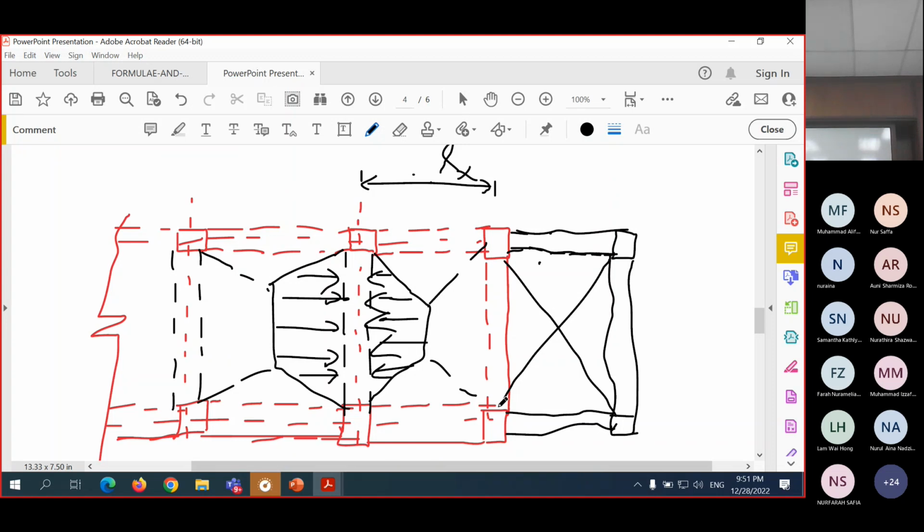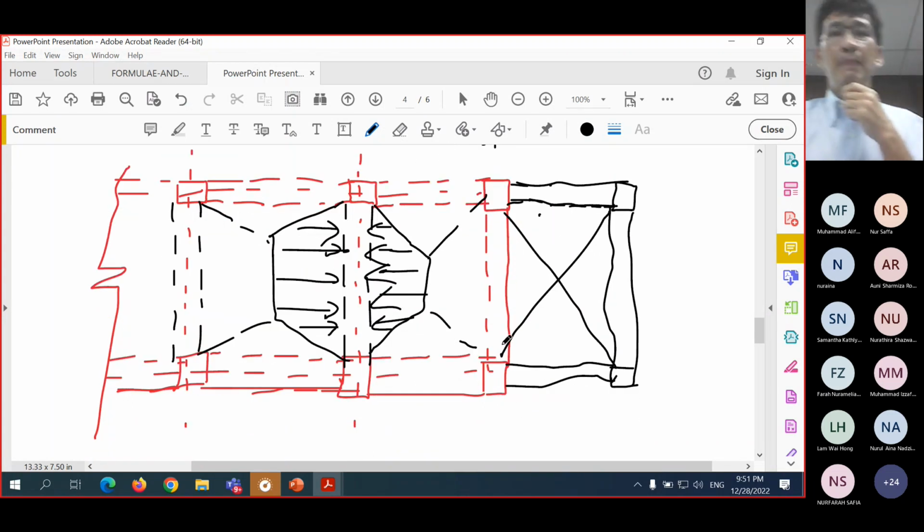depending on the standard that you refer to, sometimes for a certain thickness they give you kilonewton per meter square, which means if you look at the wall, 1 meter square with that thickness is a certain kilonewton. Then to get kilonewton per meter, you need to multiply with the clear height of the wall. Then you get kilonewton per meter. Okay. That is if the beam carries a brick wall. If the beam does not carry a wall, then the load only comes from the slab and the self weight of the beam.